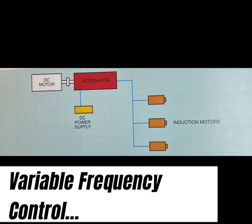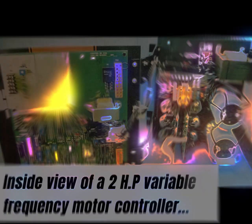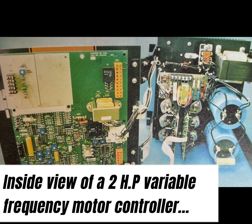Variable frequency control. One of the factors that determines the speed of the rotating magnetic field of an induction motor is the frequency of the applied voltage. If the frequency is changed, the speed of the rotating magnetic field also changes. For example, a 4-pole stator connected to a 60 Hz line will have a synchronous speed of 1800 RPM. If the frequency is lowered to 30 Hz, the synchronous field speed falls to 900 RPM.